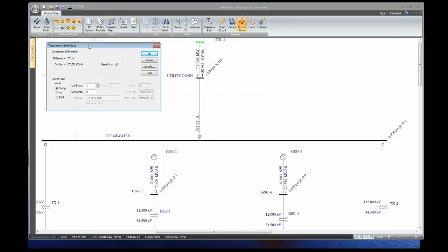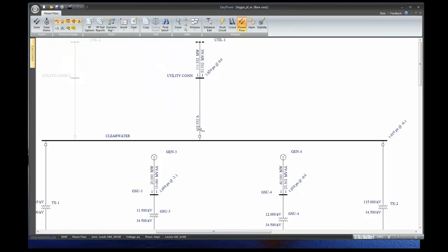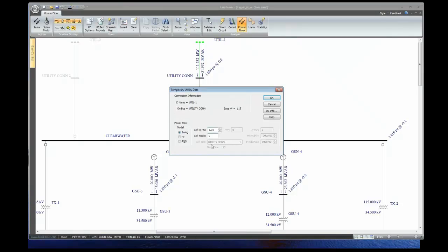So that affects this K, the megawatt, the real power a little bit, but it's a secondary effect, right? Now, if I change this back to 1.02, you'll see my amps go back up again. So it's really the voltage difference that's driving this, and that's because of the VAR flow here. And so when you start playing around with changing your voltage, you're going to want to do it in really small steps because 1% voltage change is fairly significant in the system. If you start changing it by 10%, you're going to run into issues.